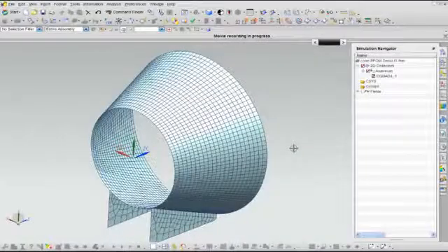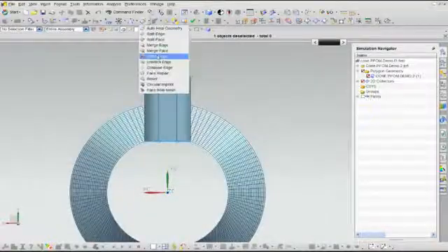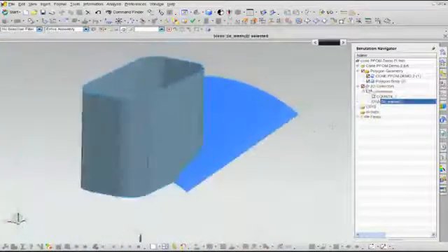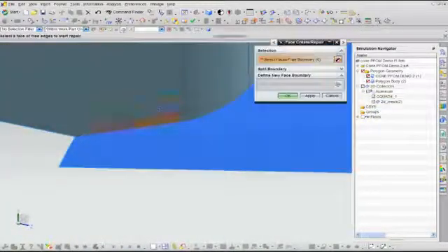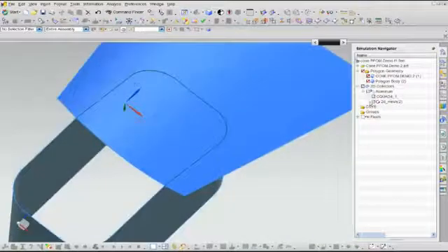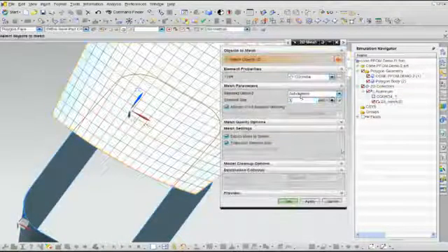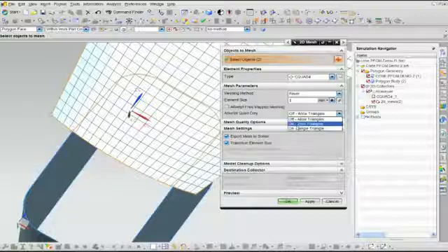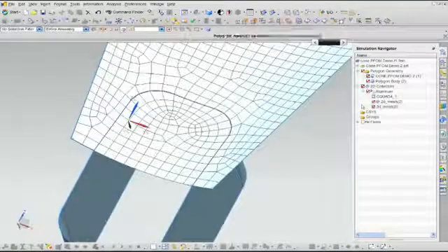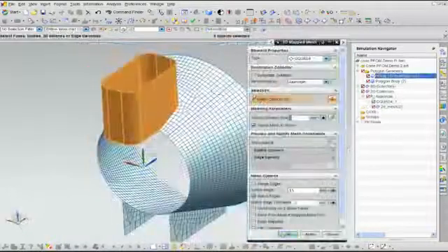Another new geometry-related productivity benefit available in NX8 for CAE is the ability to create geometry faces on orphan meshes. This capability helps you bring legacy FE models from bulk data files to life, allowing you to edit and remesh legacy data in ways that weren't possible before. You can import a bulk data file, create a surface on the elements you want to edit, add new geometry, and finally remesh the model. Ultimately, this allows you to reuse existing models more easily and save overall modeling time.